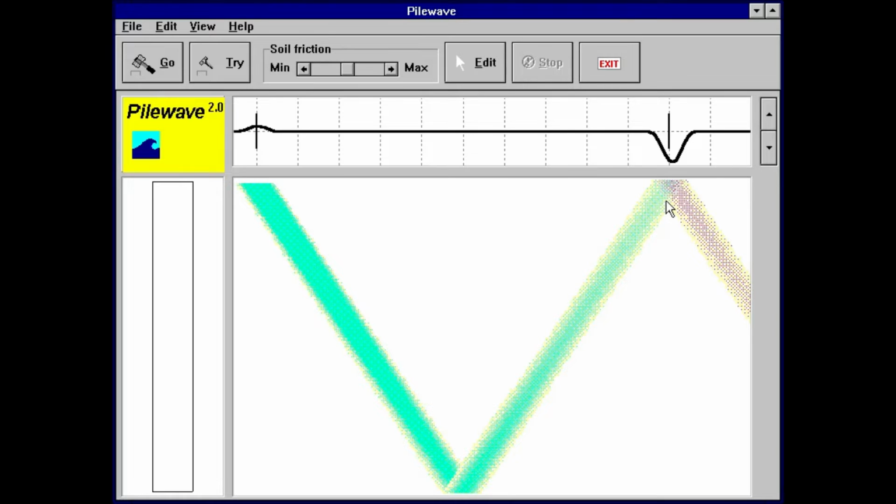In other words, as the stress wave goes down, it mobilizes the resistance along the shaft and basically dissipates energy through the shaft into the soil. So by the time it gets down to the toe, you've got less intensity in the stress wave. The stresses are dropping, the force is dropping, and that also happens when you go up.